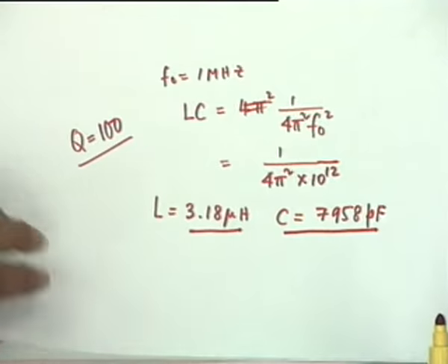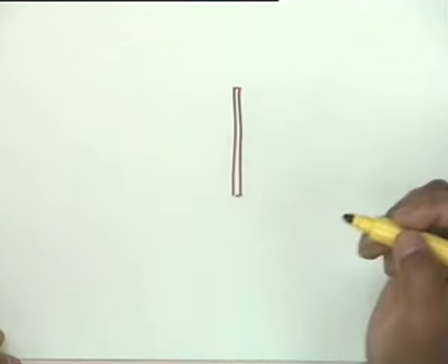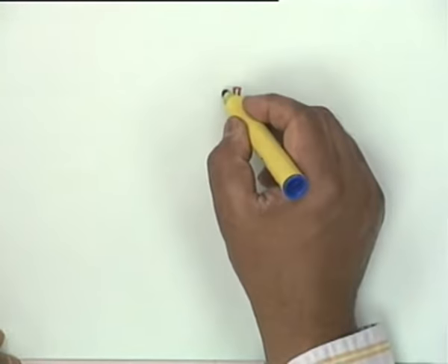Okay. So what one does is, if the values that you require are not manageable, then you use a transformer, and the transformer is usually an auto transformer, not the two coils separated by a distance. It is usually the same coil which is tapped, and at radio frequencies this can be very easily made by taking a ferrite core and winding a coil around it.